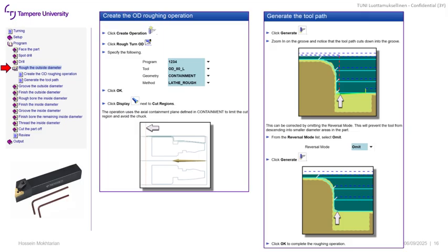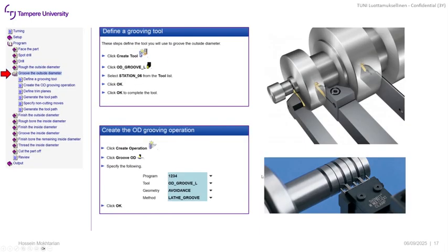While doing that, it is also important to pay attention that when we have the grooves, the tool intends to go inside the part. So a kind of reverse mode is going to be activated here, and we're going to choose an option to solve this issue so that we have a straight line and we don't plunge into the parts, which is undesired at this stage.